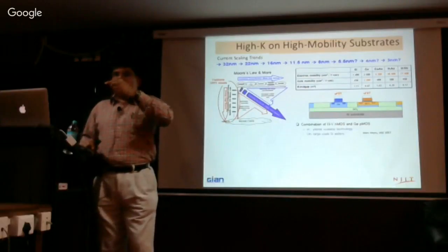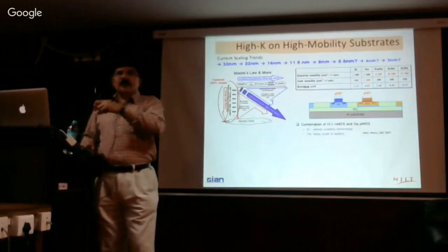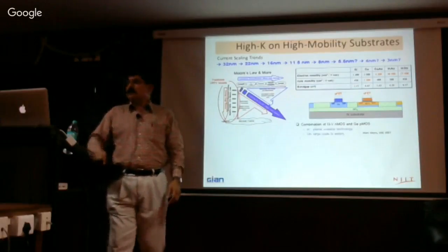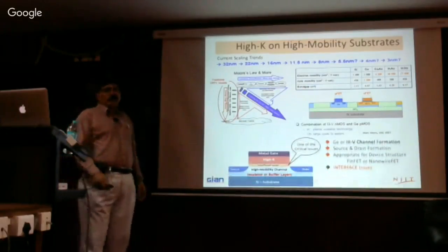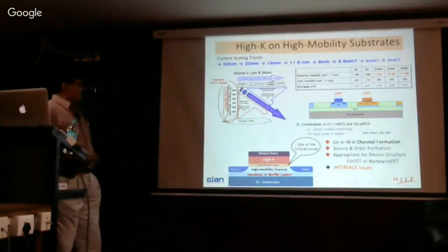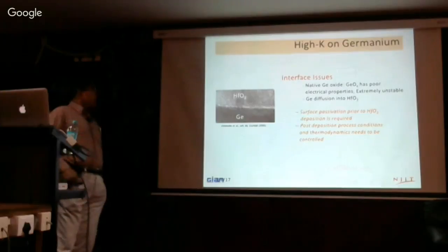So you can have one corner of the chip be a gallium arsenide chip, and the rest of it a silicon chip. So instead of two separate chips, it will be a single one. But the problem when you start those things, the biggest problem, is the interface. So this is a big critical issue: the interfacial layer. So what we did, I mentioned about this germanium thing.